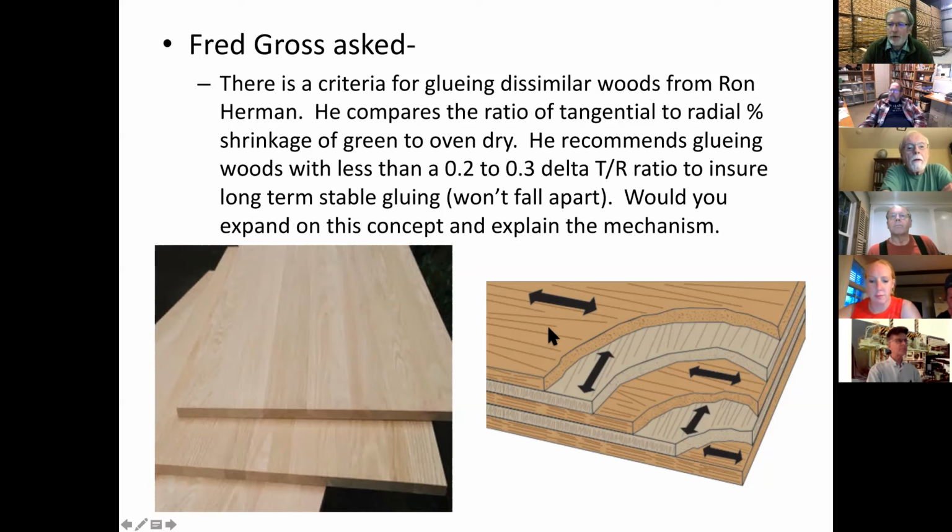If you think about plywood, in one layer the wood is oriented this way, and the next layer it's oriented this way. So you've actually got the tangential plane of reference restrained by longitudinal. That's a huge difference. From a structural point of view for the glue joint, I don't actually care. I don't believe the glue joint is going to fail if it's a proper glue joint.